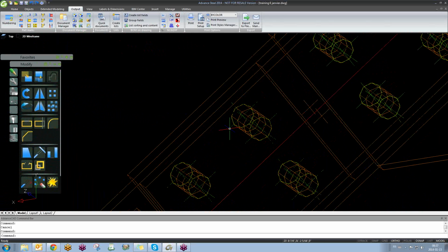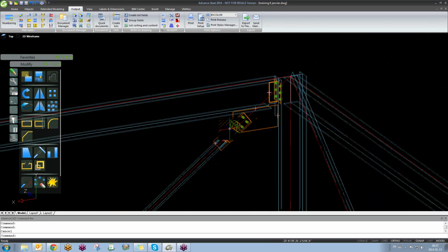Okay, no problem. So, for example, we will start with the first thing, how to rename your pieces by default. Do you see here under the Output tab you have a prefix, assign change prefix. This is the manual way. It will do that only for one piece.